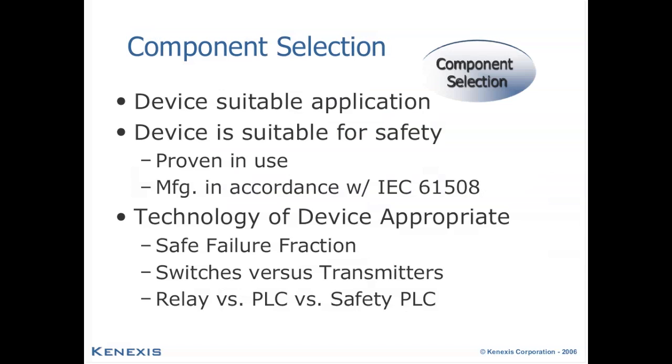Component selection, as I mentioned, there are some components that are certified for higher SIL levels. They're typically done so by the manufacturer, and a certificate would be provided by the manufacturer describing how the design for meeting, say, a SIL 2 or a SIL 3 target is in accordance with the 61508 standard, or we may be able to do a proven in use assessment of existing components in the process to achieve a demonstration that the component is suitable for use in a particular SIL application.